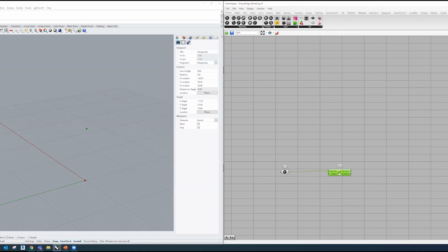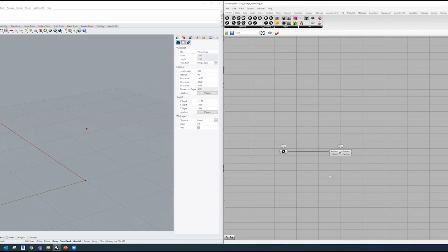So it's kind of like a workflow of steps of movements on how to create a geometry. So then if I wanted to join a line from here to here, all I would need to do is go line and go from this point that I moved to the original point, and then I draw a line.